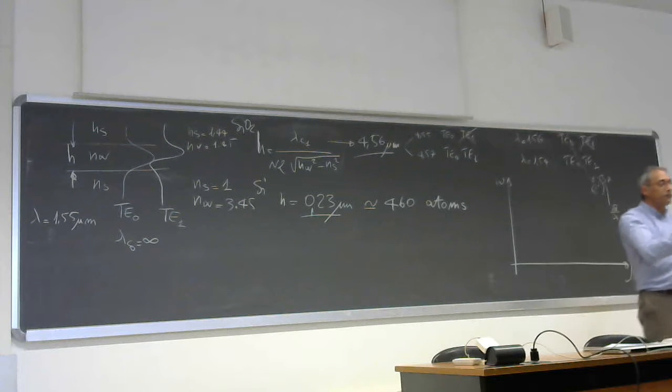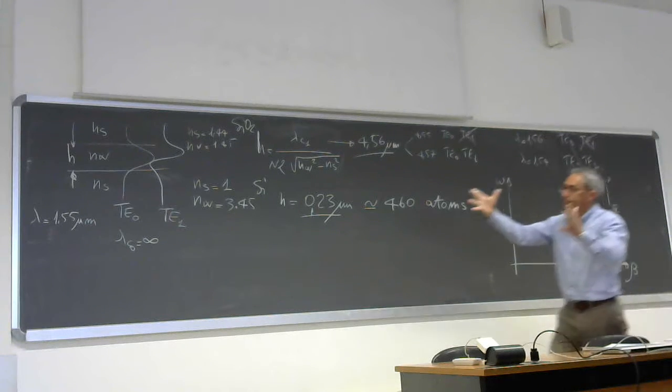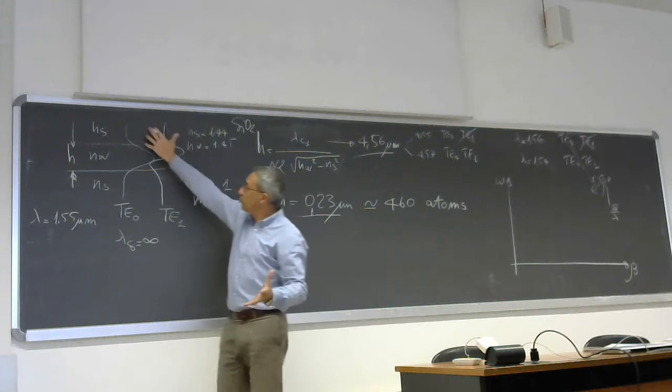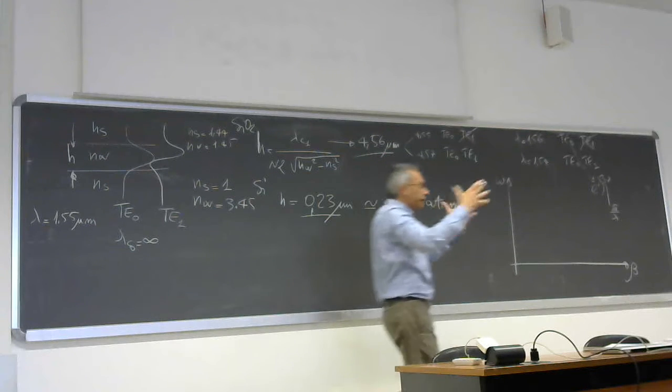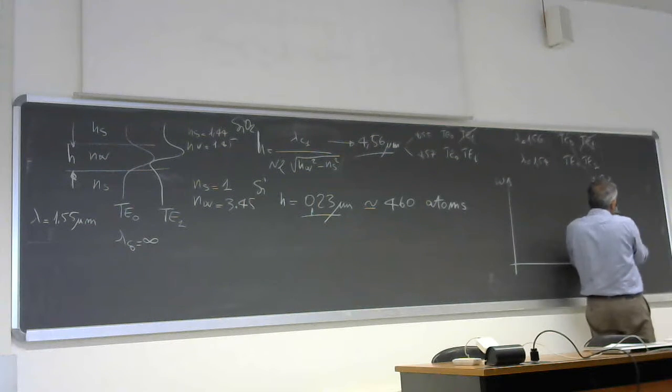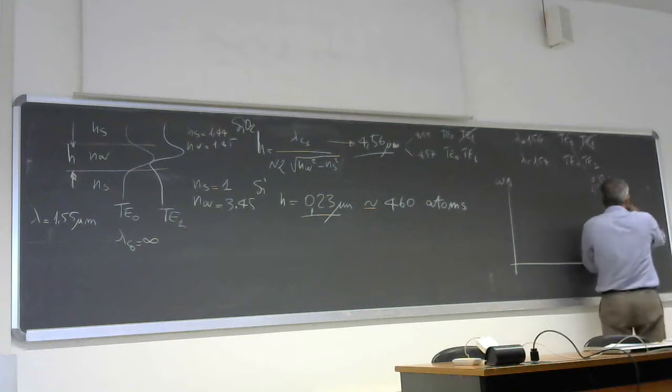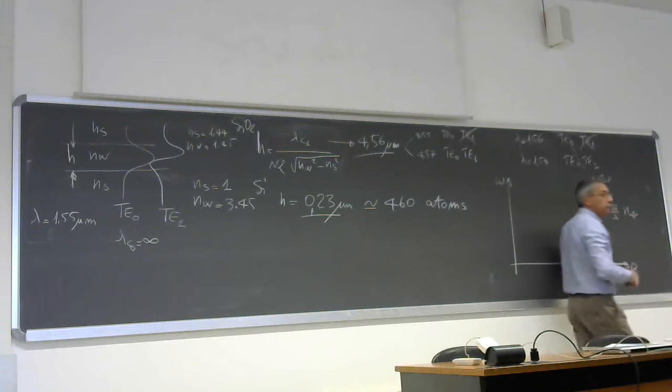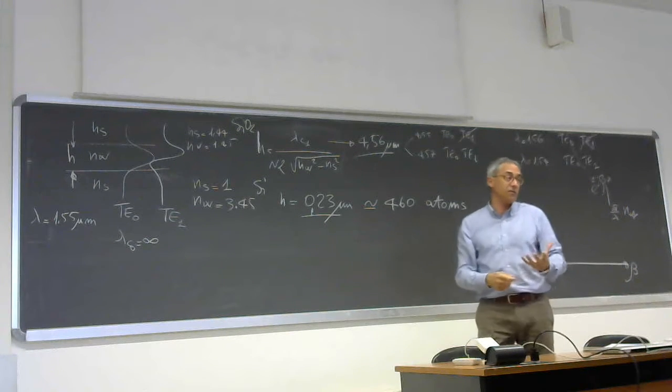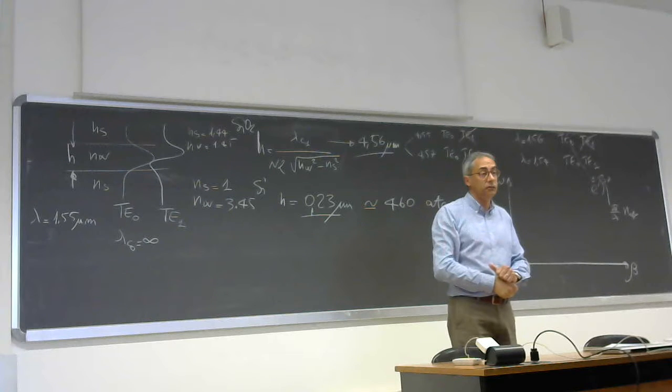This is not really a physical refractive index because the mode is spread around the core, so it's an average refractive index, but we like to write 2 pi divided by lambda, and so we add this term that we call the effective index, which is particularly important.